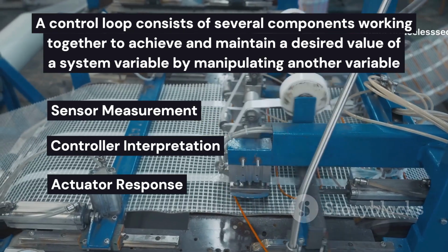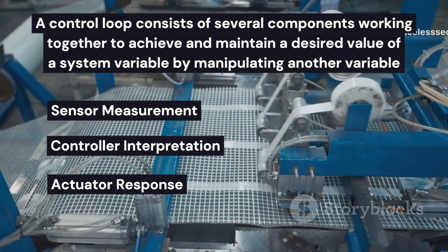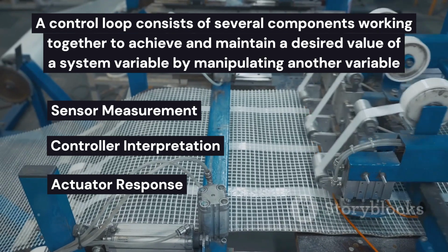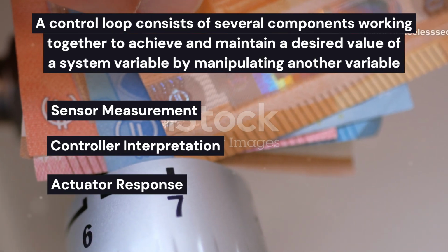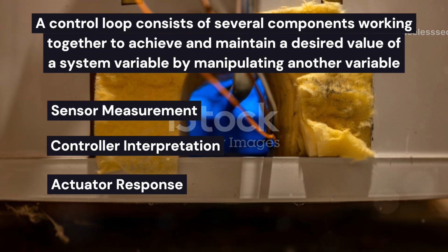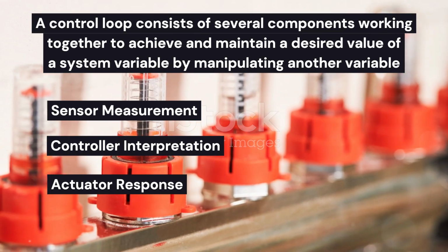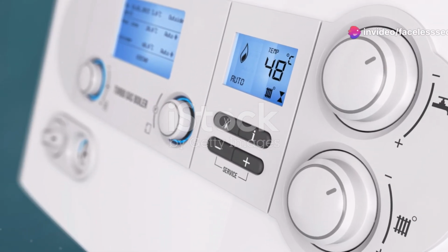Additionally, control loops can be nested or cascading, offering better performance when multiple sensors measure conditions in a control process. For example, a cascade control system in a steam-supplied water heater uses a second controller to manipulate the valve opening based on measurements from a second sensor monitoring the steam flow rate. This allows for more precise control over the heating process, improving efficiency and product quality.